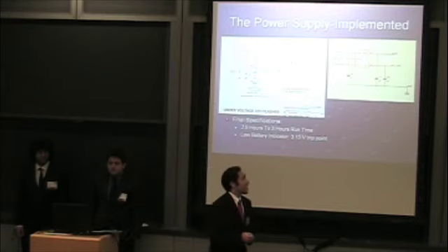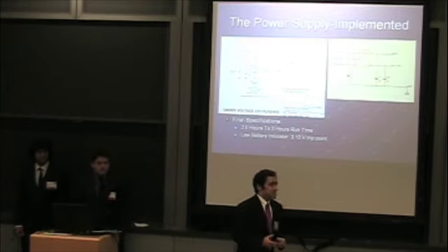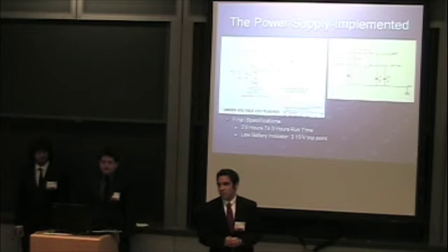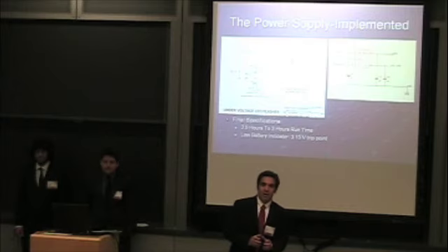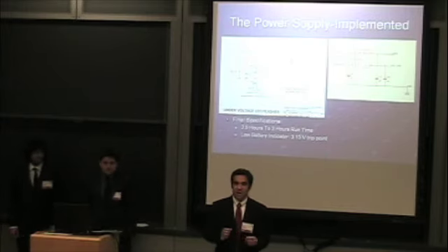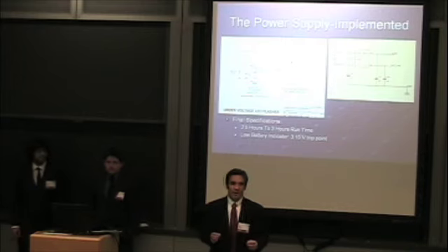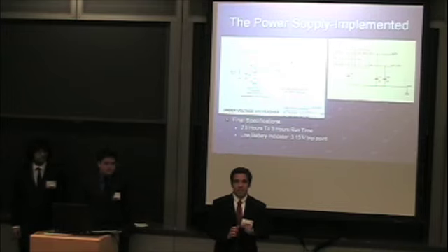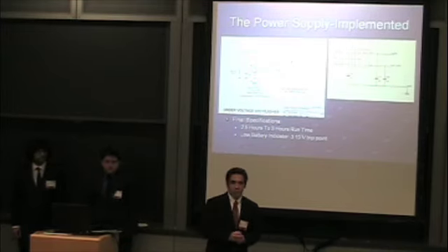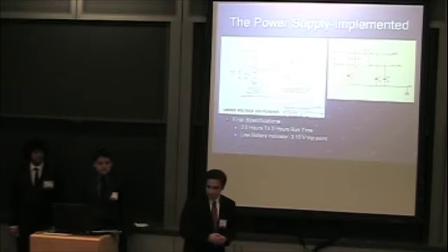And the schematic on the left is the schematic for the single cell charger, which allowed for in-place charging of the device, which is very important. We don't want the customer to be opening the device and having to either remove the load or take out the battery during charging, so it allows for the implementation of just the input from the wall wart transformer to charge the device.